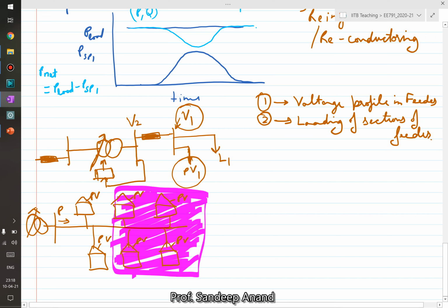And when the cloud cover goes away, suddenly all of those panels will start getting solar radiation and start pumping power. So the power produced by the panels within a distribution system has more synchronization compared to the loads which are distributed in a feeder.